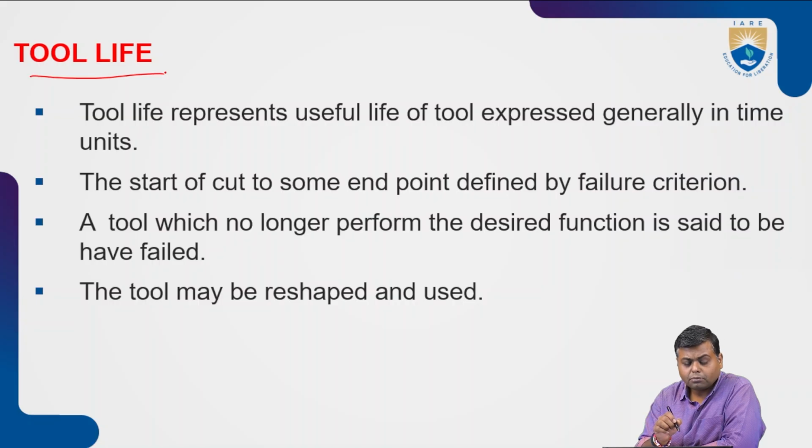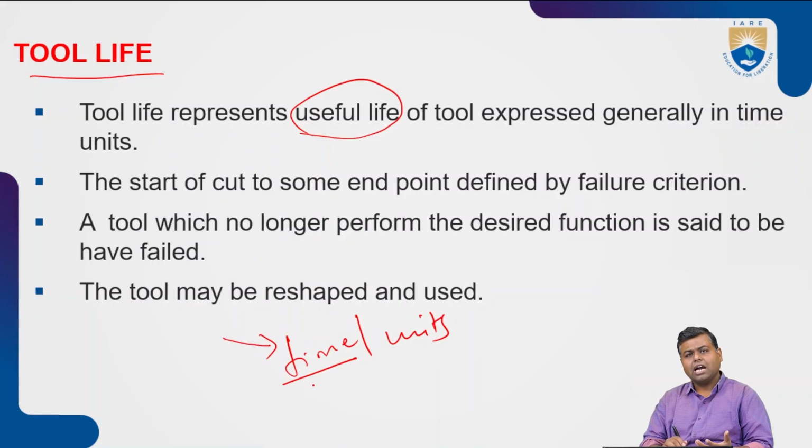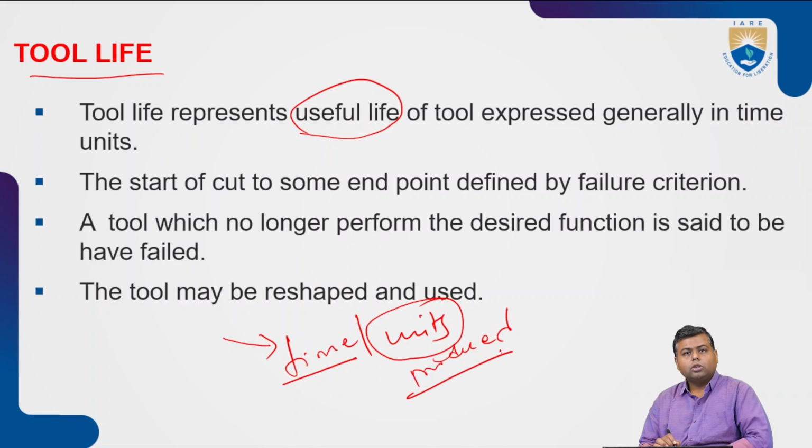tool life. So tool life is very, very important in the machining. Generally it is defined as the useful life of the tool in terms of time or in terms of units. How much time a tool is being used before getting it to resharpen, or how many products you have produced when it is getting blunt. So the start of the cut to some end point defined by the failure criteria.